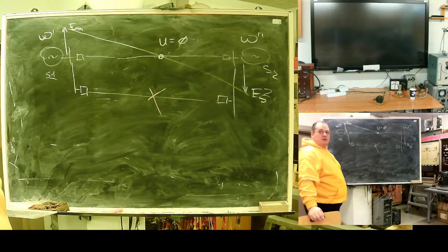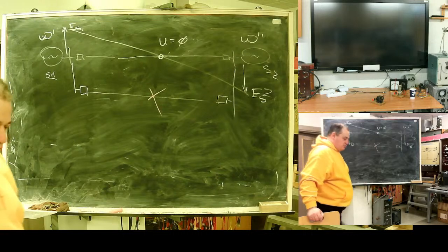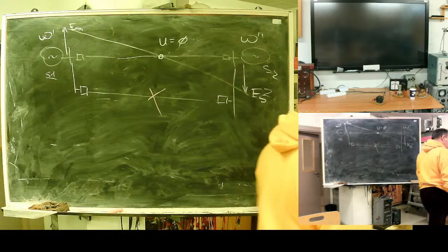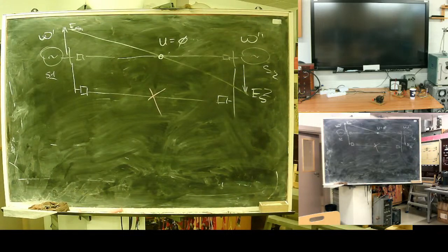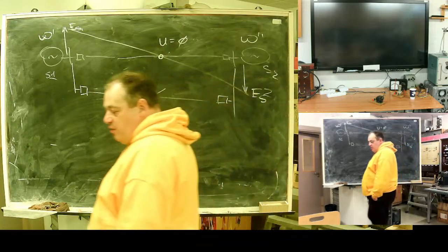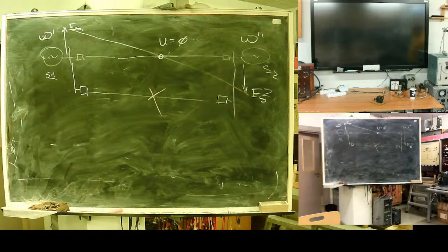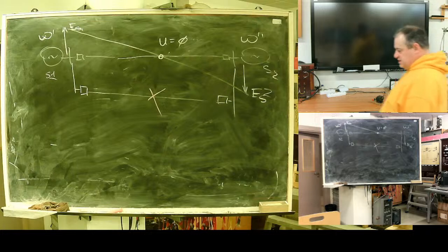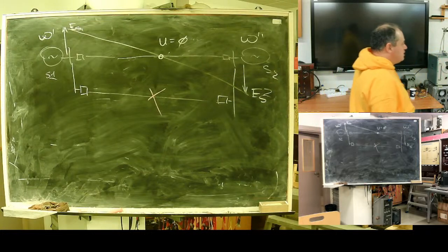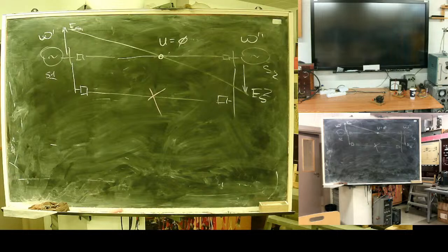There is a special, in Latvian they are AĢNA, asynchronous regime automatic. A special kind of protection to prevent such modes. Actually, this asynchronous regime protection device will separate systems. And then with the help of frequency reclosing, power balance, energy balance will be re-established, frequency stabilized, and resynchronization may occur, but it's later.